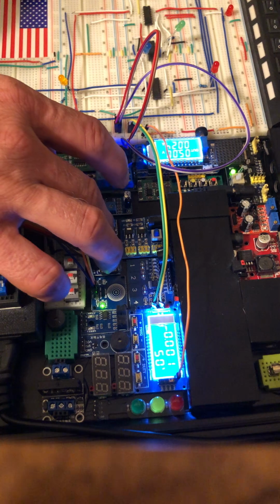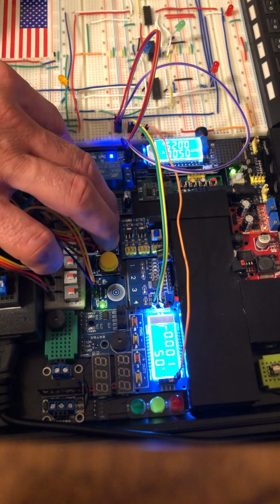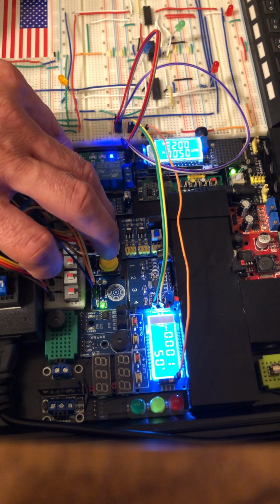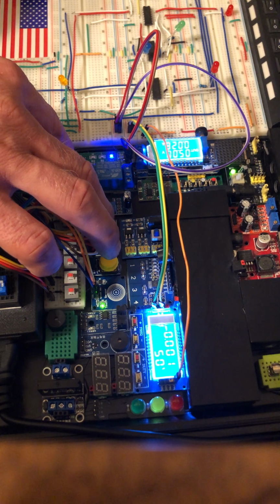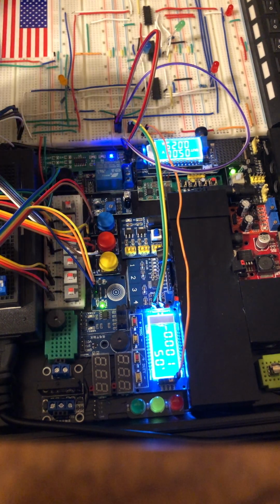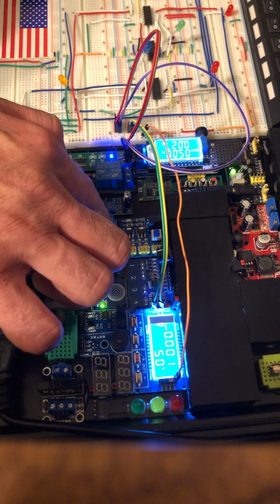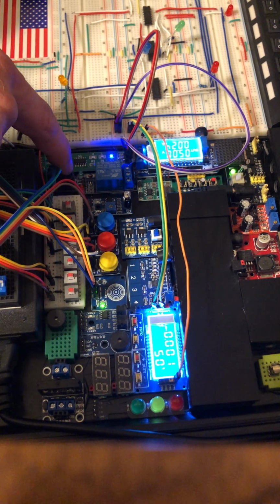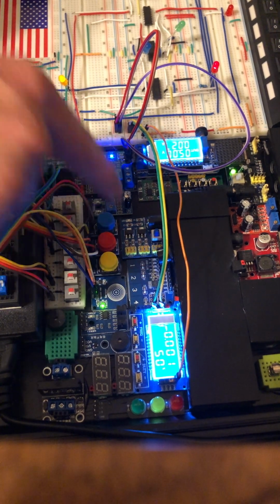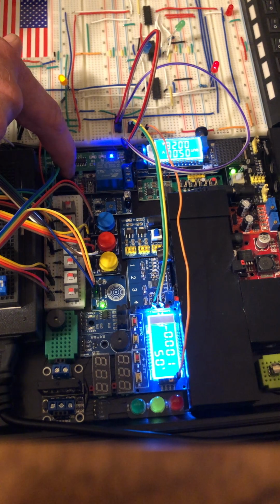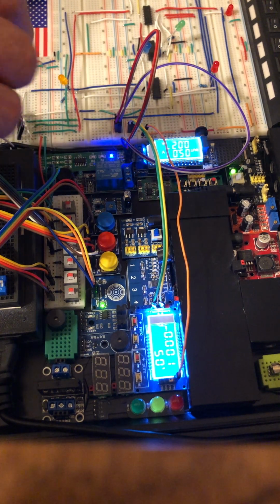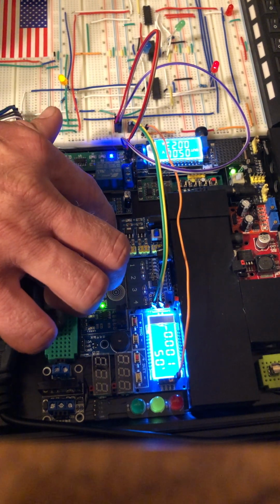Looks like we're getting a little bit of floating there. I didn't add resistors onto those push buttons, so we're getting a little signal that shouldn't happen. That should work like that. If I press it too hard, then I get some floating, and then it's going to kick on. See that? That shouldn't happen. That's why I need to put resistors in between there.